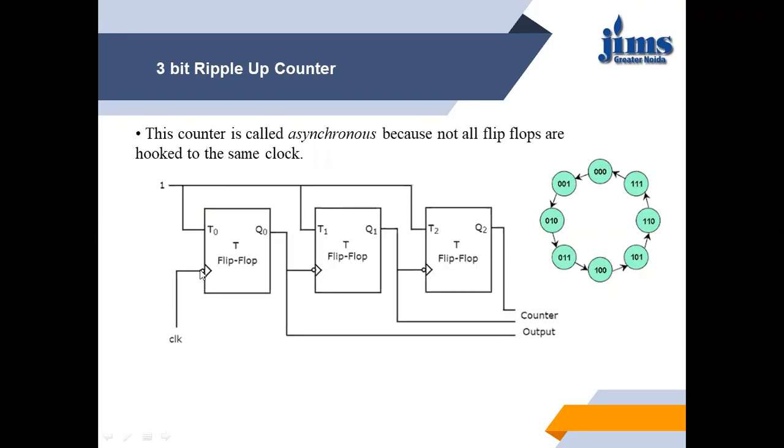First clock is the master clock. Output of the first flip-flop T0 is the clock to the next flip-flop T1. Output of T1 is the clock of the next flip-flop, and in the same manner we can continue our design up to n bits of storage.